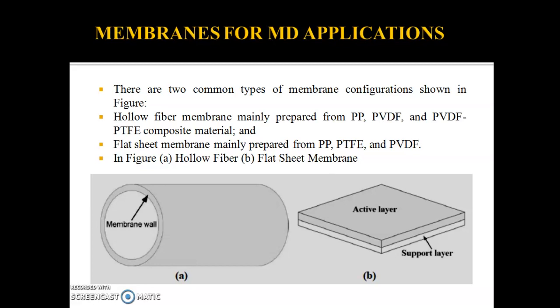but the main impediment of the hollow fiber module is its typically low flux, right? It is 1 to 4 liters per meter square per hour at 40 to 60 degrees Celsius. The low flux is related to its poor flow dynamics and its resultant high degree of temperature polarization also. So it is not used comparatively to the flat sheet.